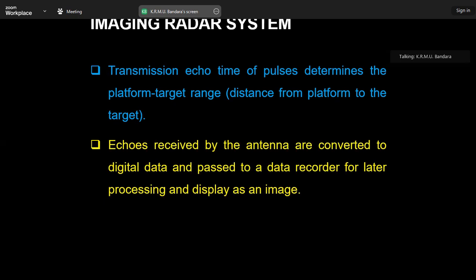But this is 0, 50 or 100: 50% is coming, 50; 100% signal is coming, 100; no energy is coming, 0. Actually, that is not 100, 50 and 0. That is converted according to the radiometric resolution. If the radiometric resolution of the image is 2 to the power 8, this is an 8-bit image, 100 is converted to 255, 50 is converted to 127, and 0 is converted to 0. That is how the optical satellite system happens.